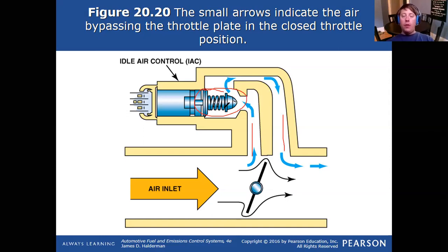So either electronically it fails, mechanically it fails, carbon builds up in these circuits, maybe it sticks in the high idle position. This is a scenario where you can have a car that wants to drive at 40 miles an hour without your foot on the gas at all. Customers might complain of you shifted into park, from park into drive, it bangs. Pay attention to the engine RPM. Most customers aren't going to pay attention to the engine running at 1600 RPM. They might complain that it's running a little bit loud, okay?